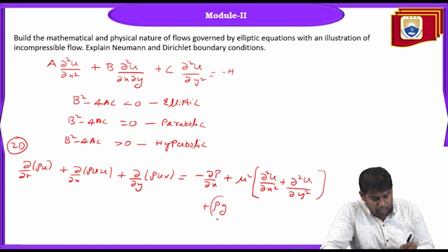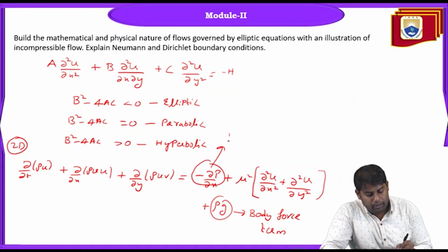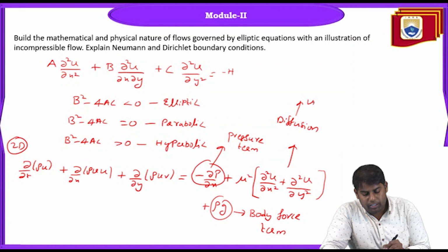Let's say this is the body force term. This one is the pressure term. This is called the diffusion term, which is coming because of viscous effects.